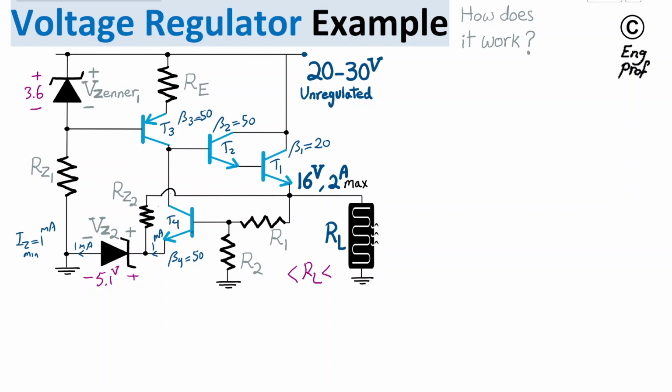Of course, there is a reliance issue with respect to this VBE, or base emitter voltage of this transistor T4, sensitivity to this one. So one of the mechanisms to counteract that is via RZ2, which I'm going to talk about. But for now, let's focus on this transistor. When T4 is on, you can see there is plus minus 0.7 volt base emitter diodic voltage drop there, a PN junction.